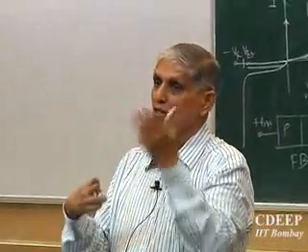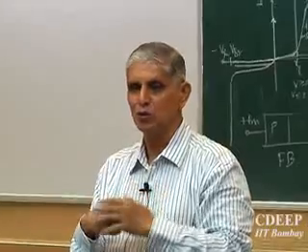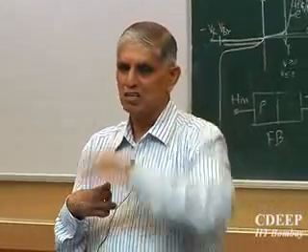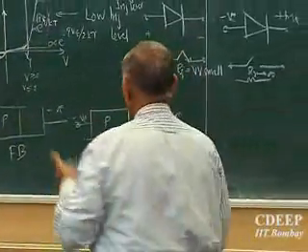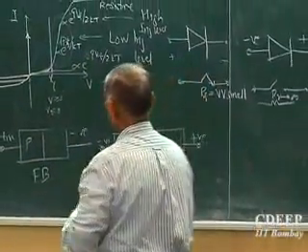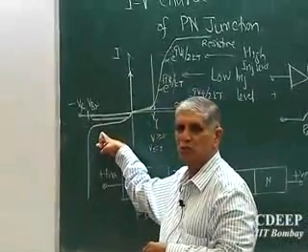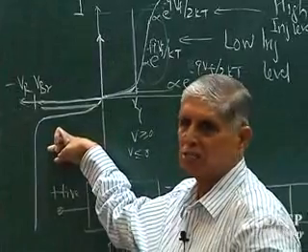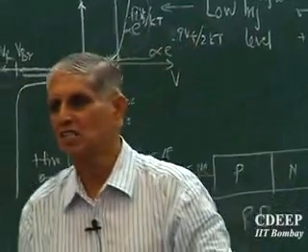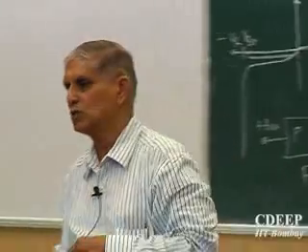However, if you keep increasing reverse bias, it doesn't remain so. At a certain value, it suddenly starts shorting. This is called breakdown. The maximum reverse voltage the device can stand is called its breakdown voltage. Is that clear? Typically it can be 25-30 volts for transistor junctions, a good diode may have 100 volts, and good power rectifiers can have as much as 5000 volts.